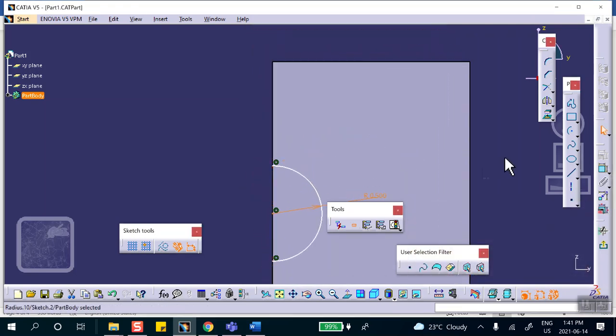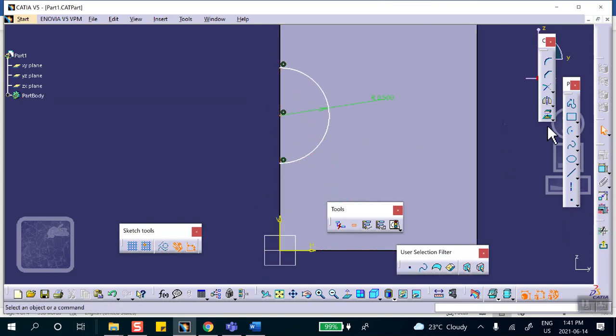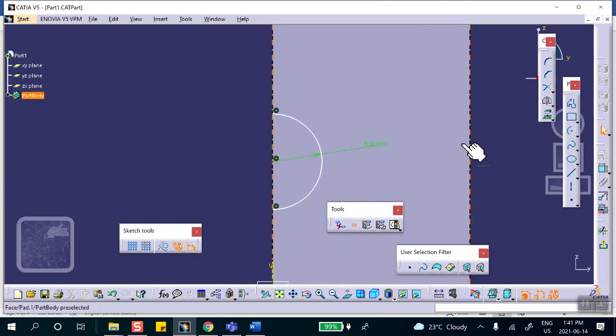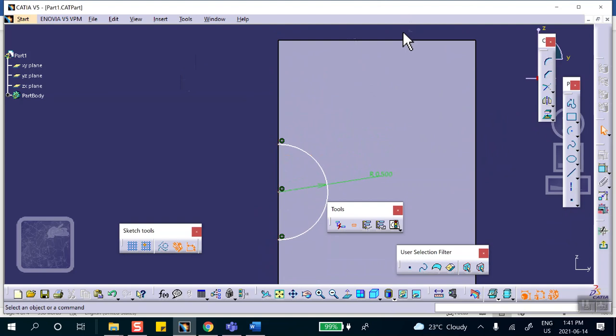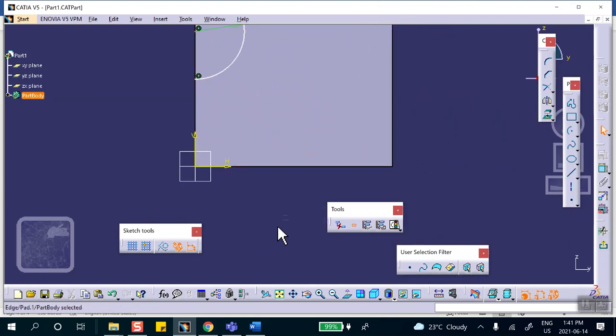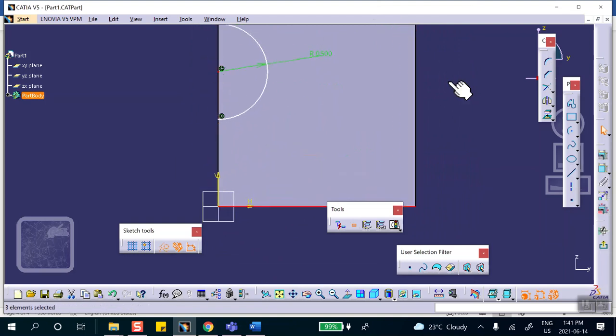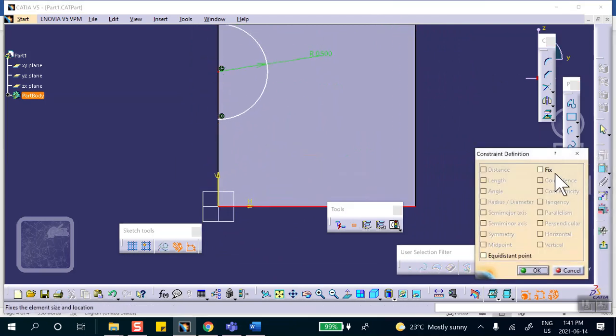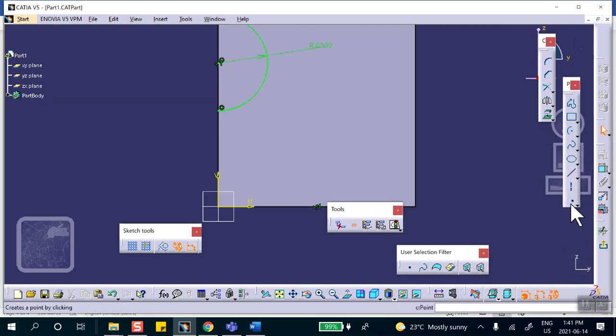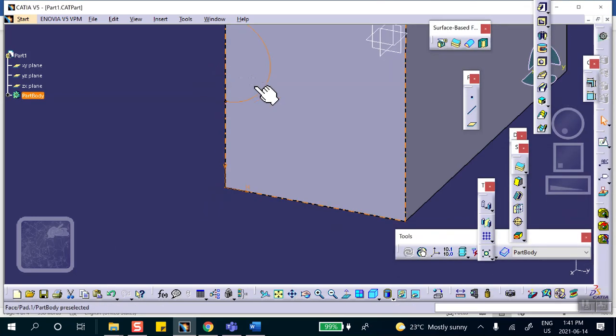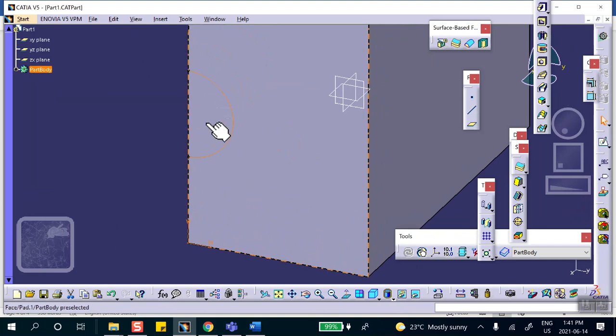And it's symmetrically placed between the top and the bottom. You can either put a dimension or you can use a constraint, entirely up to you. I'll use constraints. So top line, control bottom line, control the center, and I'm going to make it symmetric. I'd rather use these constraints instead of dimension, but you could have made dimension equal to 2 from the center all the way down, or 1.5 actually.